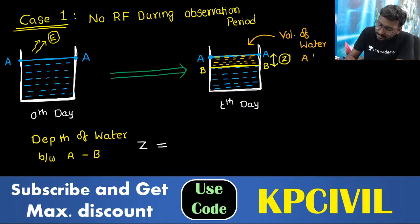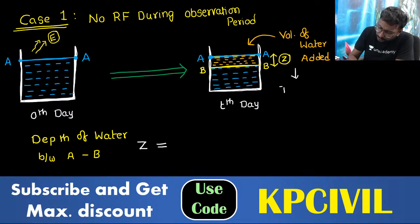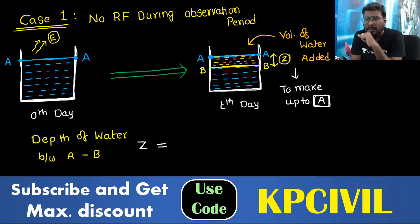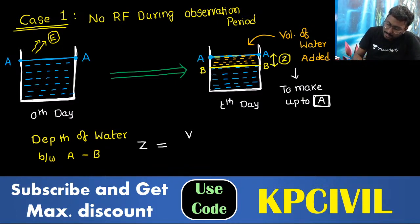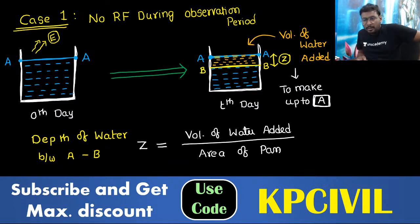Volume of water added. For what purpose you are adding water? Tell me. Volume of water added to make up to the stipulated level A. Then you take how much volume of water added. That volume of water added divided by area of pan is equal to Z. You understand? You are getting depth.